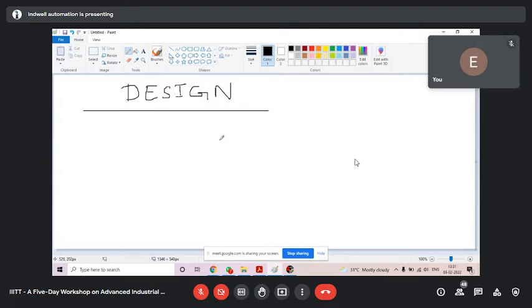Three PLC brands you are going to interface to your SCADA software, to one laptop suppose. So obviously you will connect these three PLCs to three different communication ports. So you will have to very first select PLC brand, that is driver selection.